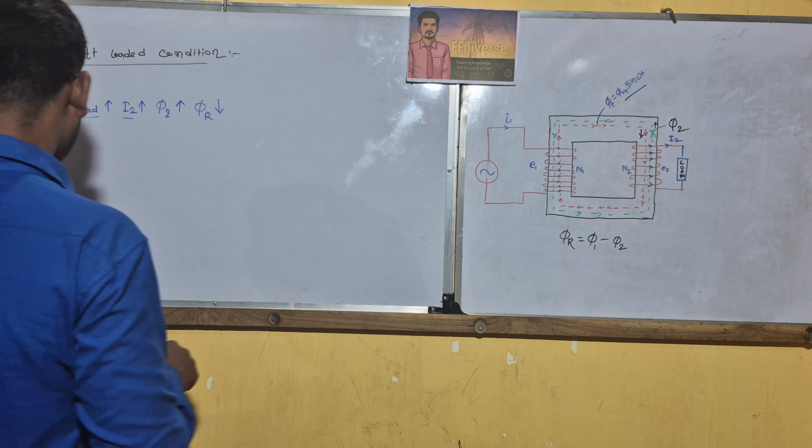Okay, if the voltage and frequency do not change in our supply, if the V by F ratio is constant in our supply, then our main flux is also constant in our transformer.